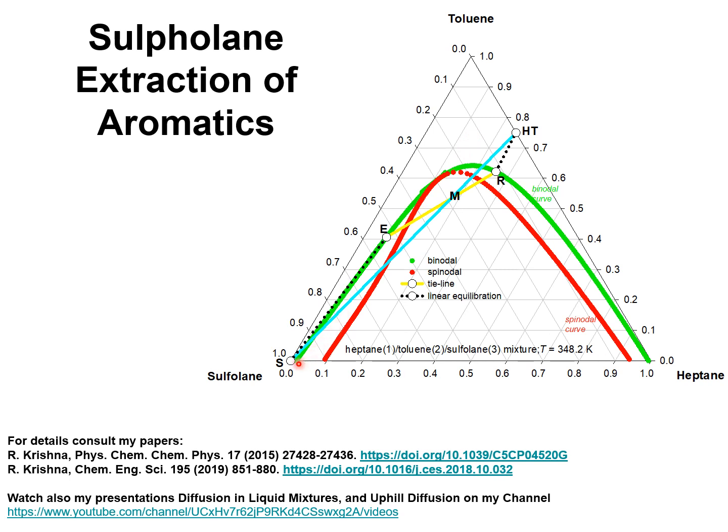There is, however, a range of immiscibility within the binodal envelope marked green. The red line denotes the spinodal curve that delineates the region of phase stability. The area between the binodal and spinodal curve is a metastable region. This area here is also a metastable region. The area within the red colored envelope is an unstable region. Any mixture with a composition in this region will split into two phases.